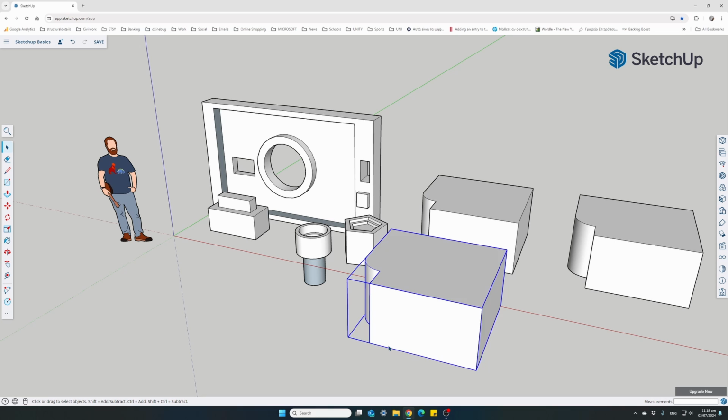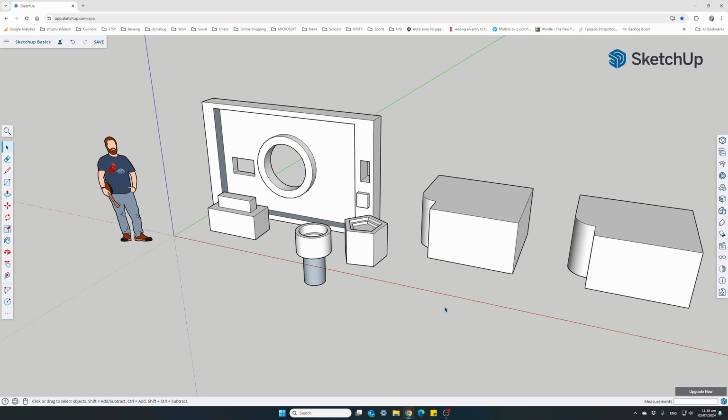For the rotate function, let me take this out of the way. Select the object we want to rotate, and there's a rotate tool here again in the toolbar. There's 2 rotate arrows in the red color, or use the letter Q on the keyboard. So rotate, our cursor will change into an angle measurement tool, the protractor, and it's shown with the color blue.